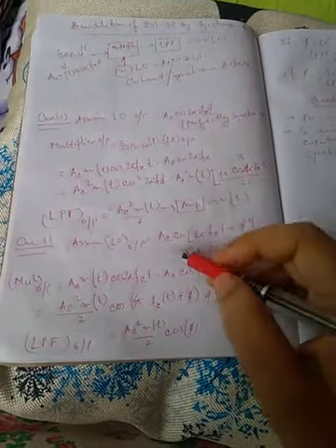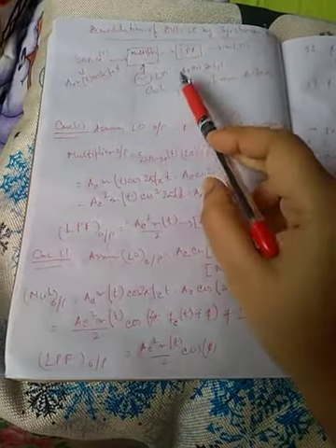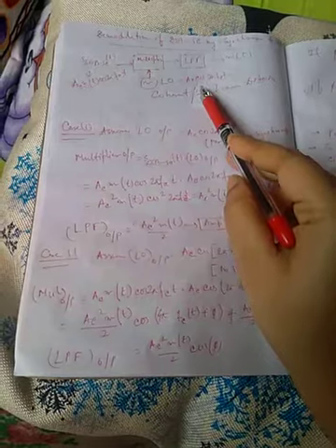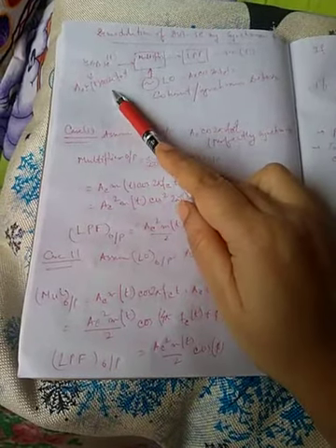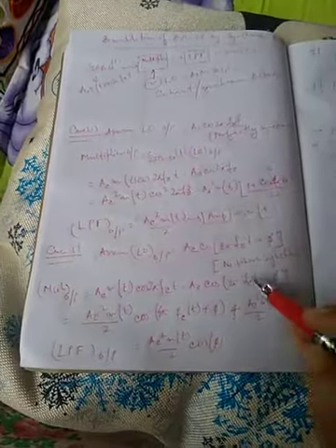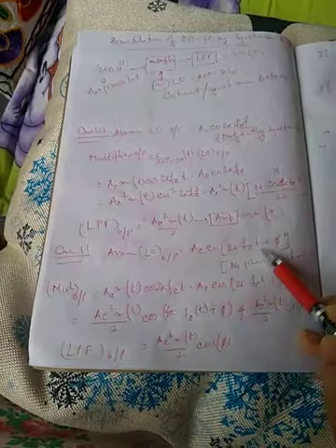Now coming to case 2, that is if this local oscillator output, this carrier signal, is not perfectly synchronized with my input carrier signal, then how will it be? If there is a phase error, my local oscillator output is Ac cos(2 pi fc t plus phi).